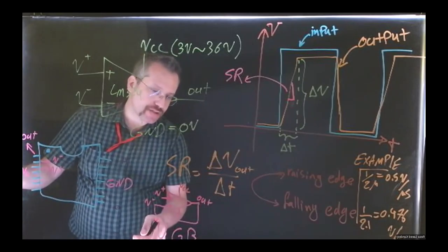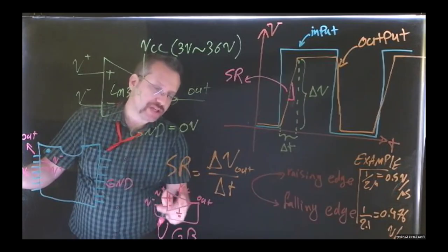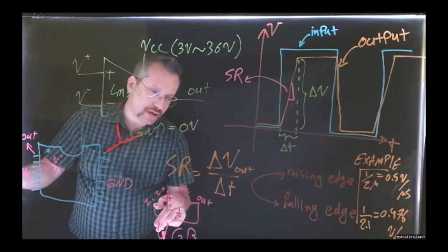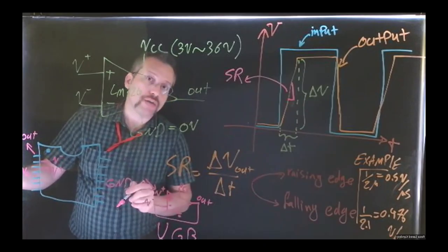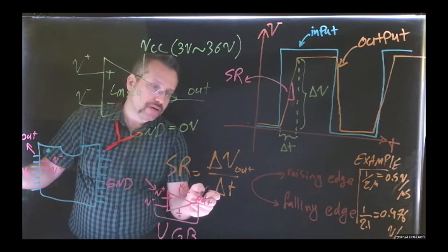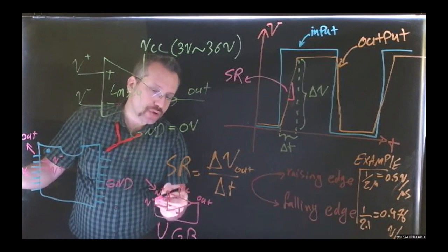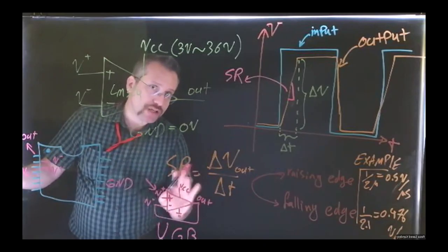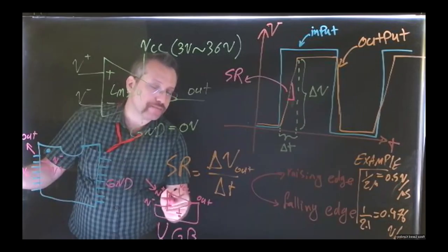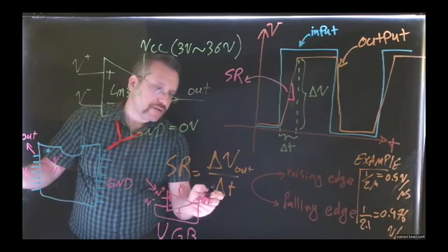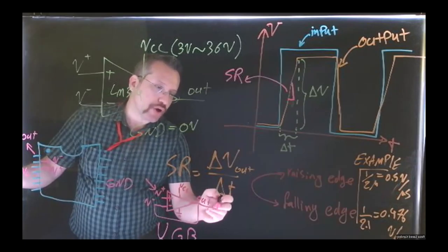It's not a very complicated system. So we have our op-amp, and VCC and ground are already known. We inject the input to the non-inverting input, and we connect the output as a feedback, without any resistance, a direct feedback to the inverting input. Okay, and we are going to measure the output here.